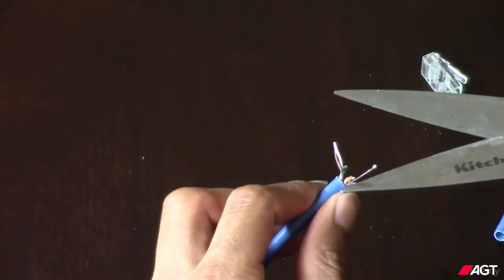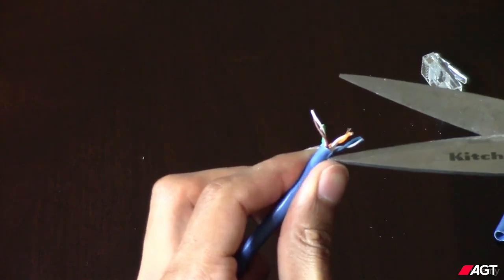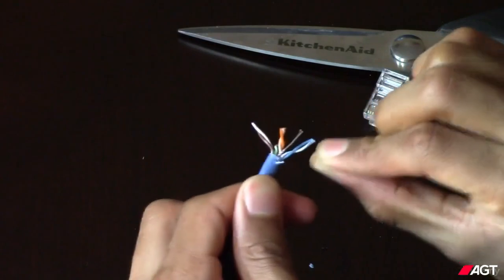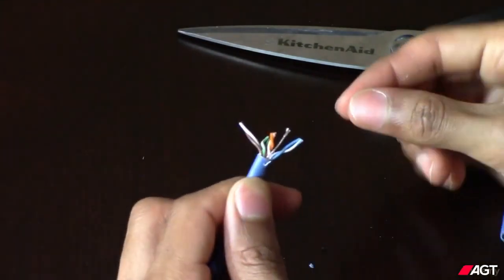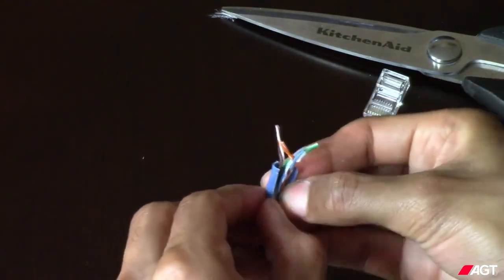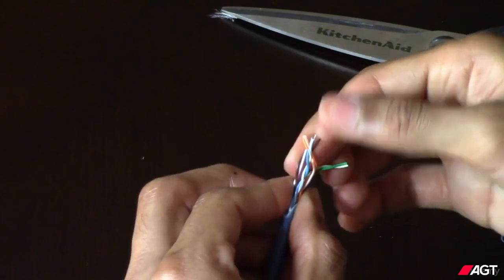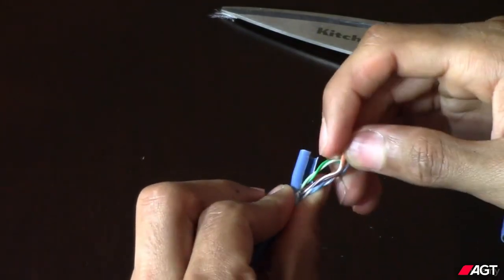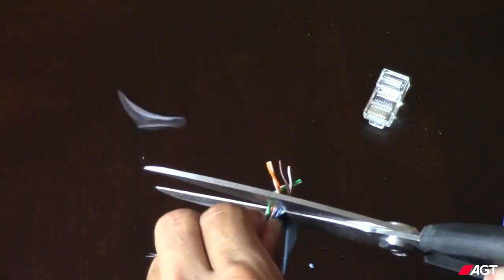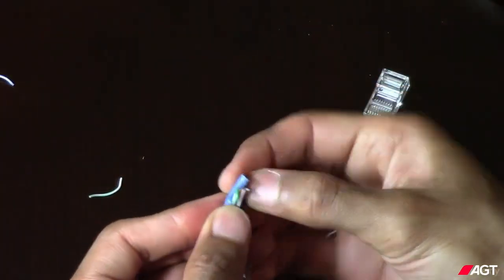Take your scissors and cut a small slit into the shielding. You're going to use this as a guide for your nylon ripcord. After ripping off more of the sheath, you'll want to cut off the part of the wires that you spliced into with your scissors. This is what I meant earlier when I said don't initially measure with the connector. Using the part that you cut into with your scissors could save you some time, but it's ultimately going to come back to haunt you if one of your tests fail.